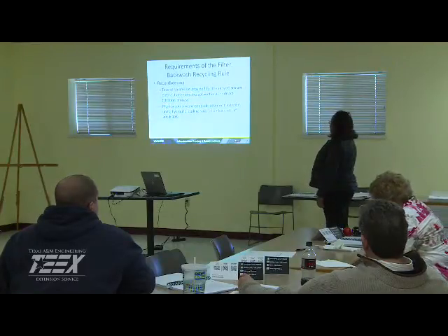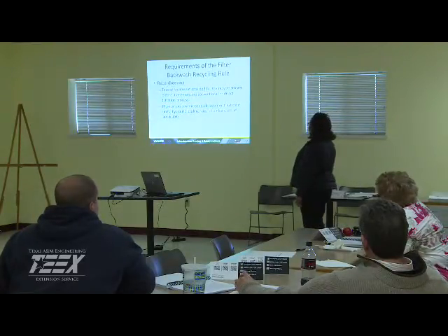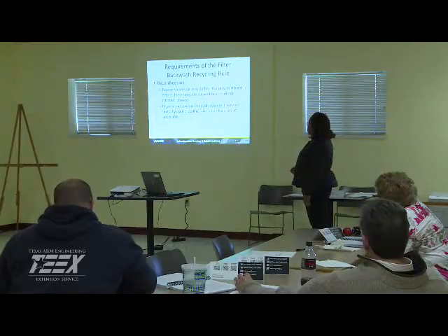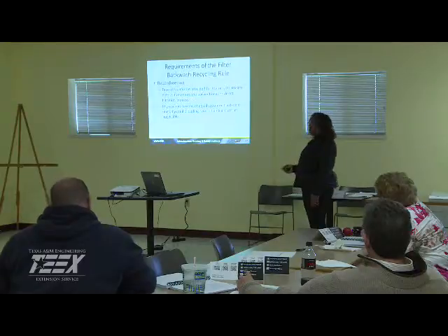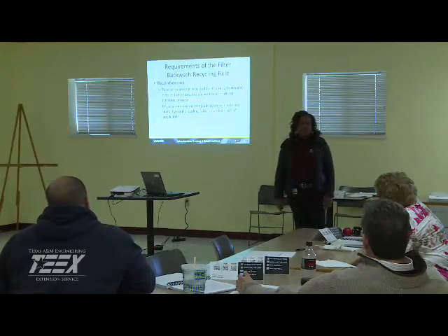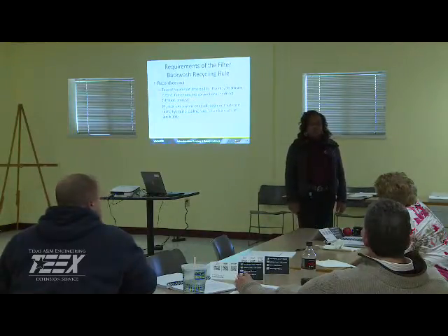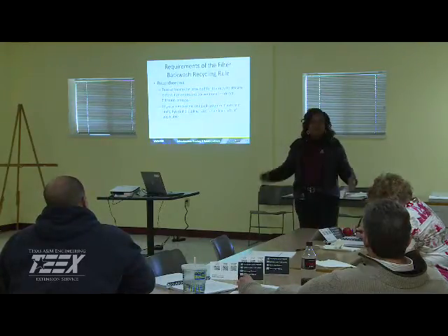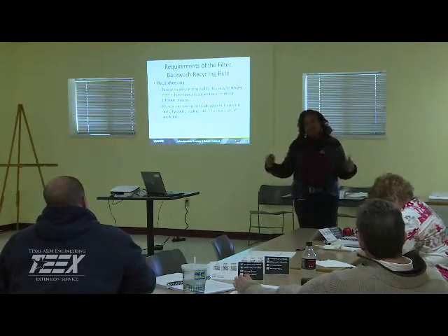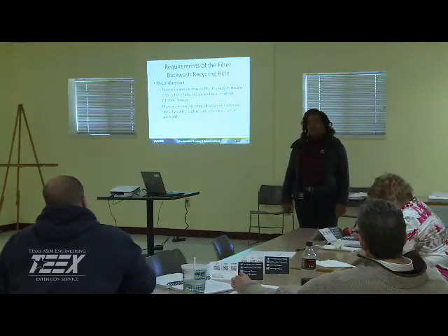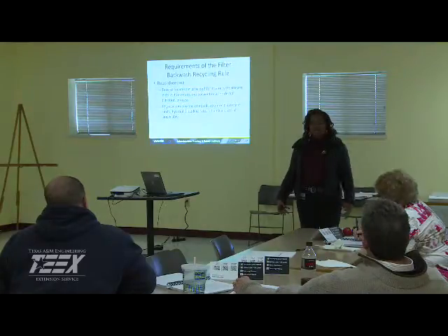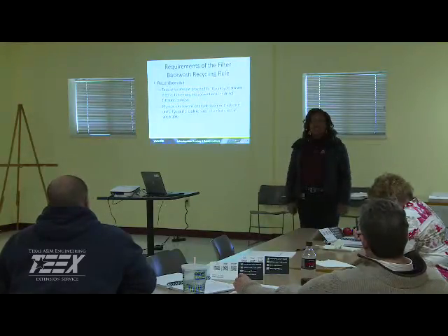All right, record keeping: the time of treatment provided for the recycled streams before it re-enters the conventional or direct filtration process must be recorded, as well as the physical dimensions of the treatment units, your hydraulic loading rates. Do you know that? Your hydraulic loading rates? What's the system designed for? Because again, the dimensions of your basin, in other words, it goes back to the recommendation. If I'm putting flow through that filter, then what they recommend, what does that do with efficiency?